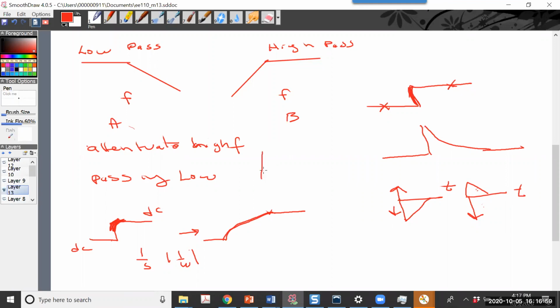Where here, that is the impulse response of an RC circuit, but that could be approximated like this. h of t starts at 0, goes to something, comes back to 0. That's like a low pass shape, which will round things out.